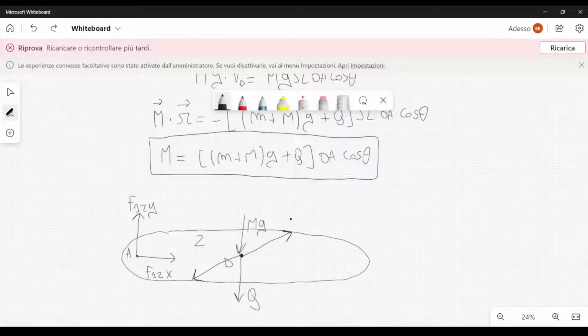Let's call it, well, this is just the mass of the body times AD, so this is the inertia force, and it is just equal to m times the magnitude of the centripetal acceleration, which is omega squared OA. This is the only acceleration that we have. It is centripetal. There is no other acceleration because omega is a constant. So I will not delve into the details of this, but the acceleration of this point is equal to the acceleration of the point A.